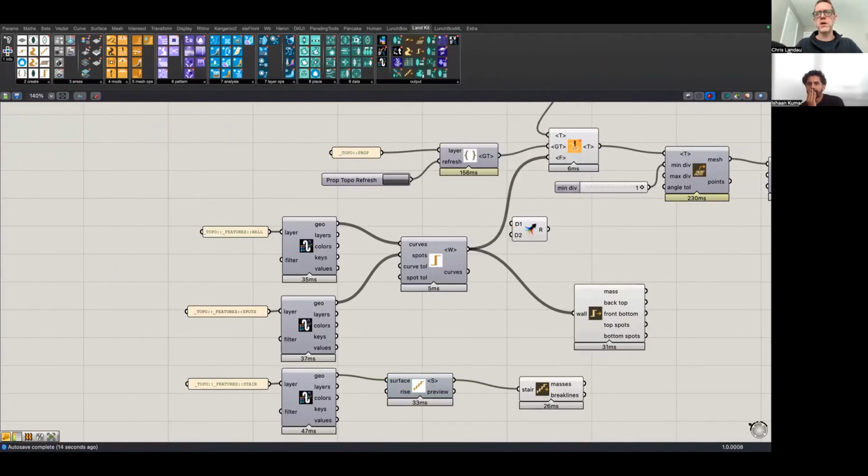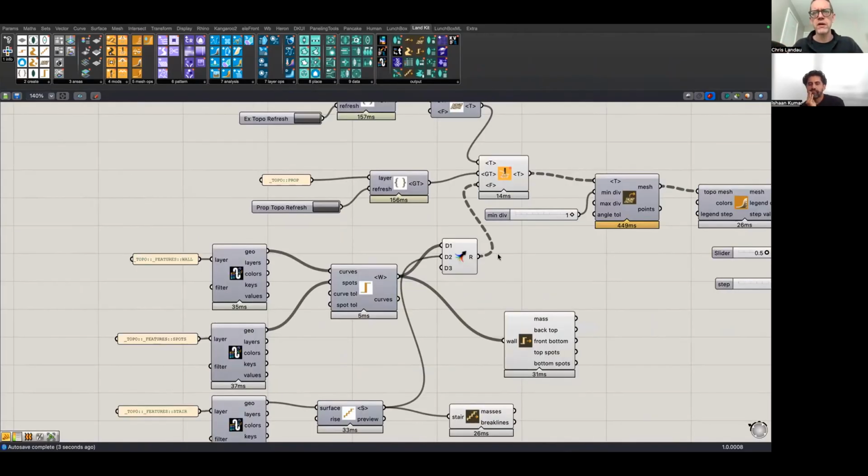So what I like to do is do a merge component, and that lets me have multiple inputs that I can plug in really easily, and I'm not doing shift or whatever. But see this dotted line? This is a tricky thing. Because these are at different branch levels, they split the data. It's almost like multiverse. It splits it into multiple realities, and each one has a different topography, right? So what we want to do is flatten this into one reality. So right click and say flatten.